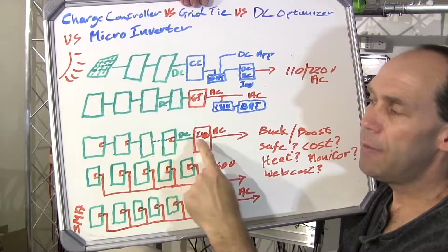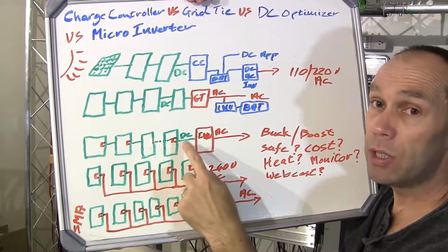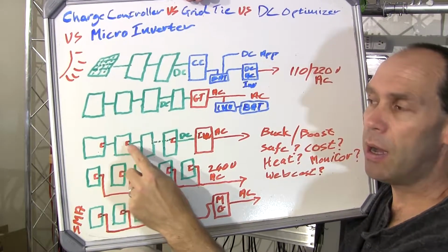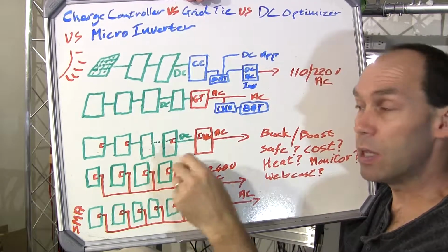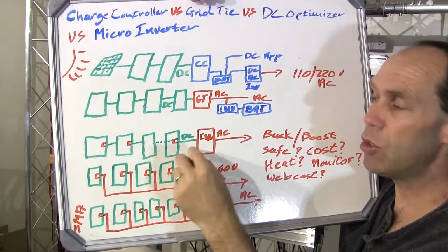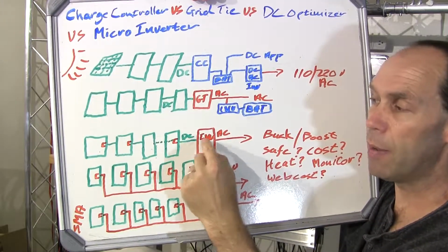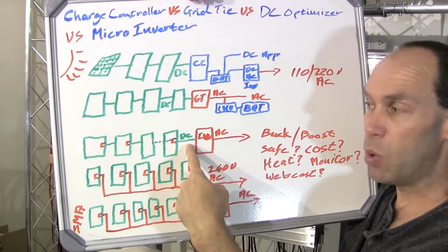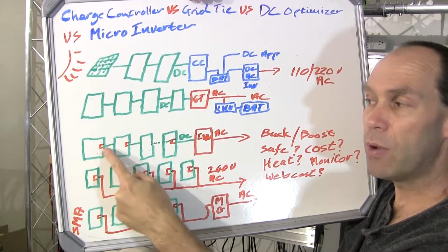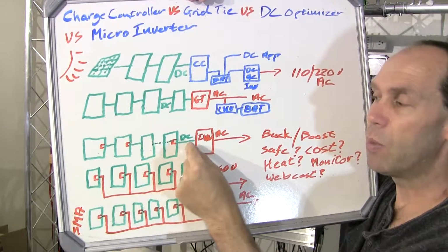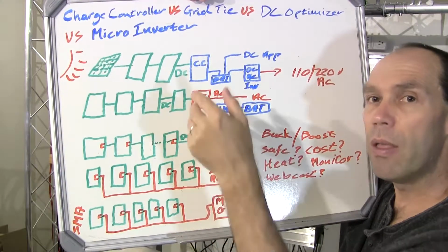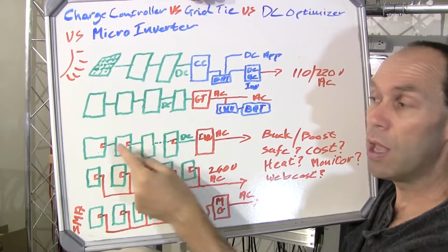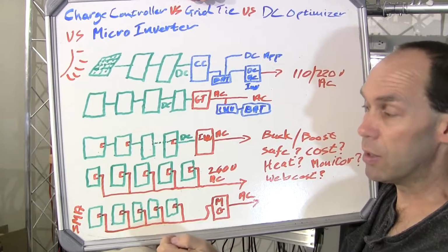As an added safety on some of these systems, and it's something to look into, because you could potentially be sitting with very high DC voltages on your panels if you've got a disconnection. Let's say you're going to do maintenance and you go and switch off your inverter. You could have a very high DC voltage at this point. But often they've got safety built into the optimizers where if they don't see the inverter, they'll then shut down their production. And that's certainly something to look for if you are looking at these kind of solutions.